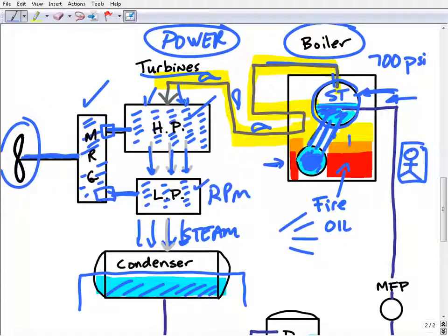You're going to rust out this boiler in a matter of hours, and actually, that's happened where engineers, for one reason or another, lost their way on the water specifications for a boiler, and you can have oxidation going on, and you can rust out tubes. We all know what happens when aluminum or steel rusts: it gets weak, and then eventually you have holes.